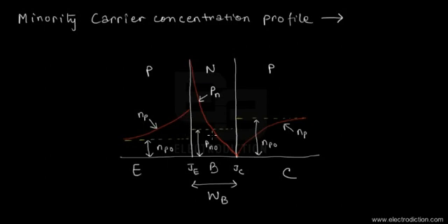over here. But as the current starts flowing from the emitter into the base, and similarly from the base back into the emitter due to the electrons, we can see that near the emitter junction there is a sharp rise of the electron concentration that comes in from the base into the emitter section, constituting the electron carrier component of the emitter current.